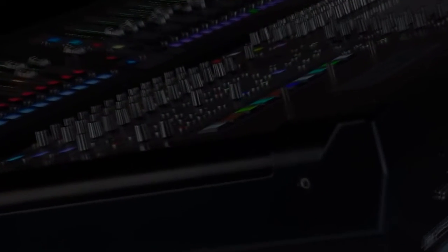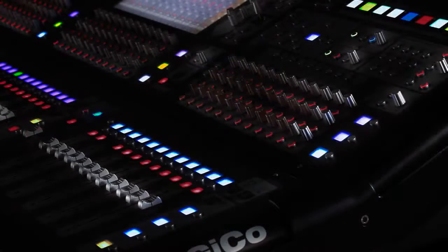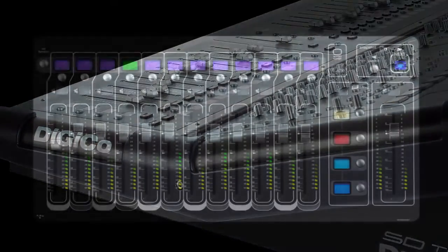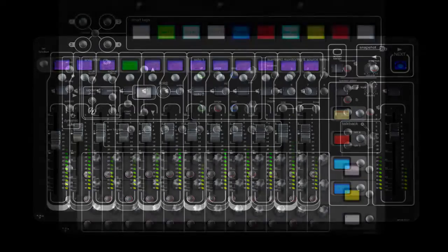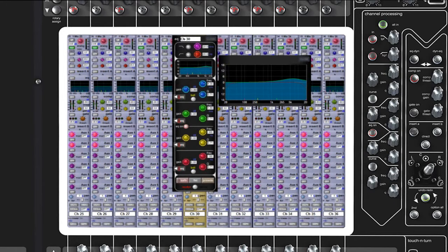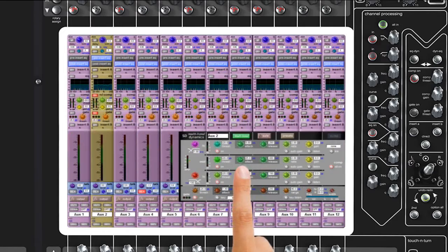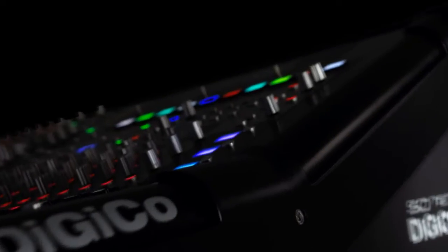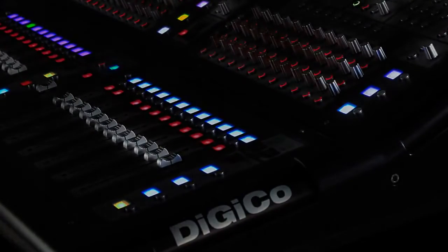It comes with all the refinements you would expect on any DiGiCo console, but with some exciting new options and an application-specific feature set. To start with, the work surface is constructed from anodized aluminium, overlaid with polycarbonate panels to provide clear and concise user feedback. A large 15-inch digitally driven touch-sensitive screen provides the user with feedback, as well as fast control of all the main parameters. There are 37 100mm touch-sensitive faders to allow fast access to the large number of channels and outputs that can be assigned across the surface.